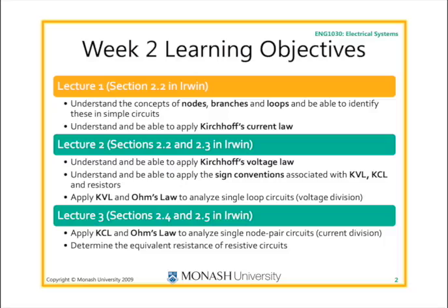Analyse node A, I'm going to say the sum of the currents entering this node is 0. Write down the equation in terms of the currents coming in. You could then jump to another node in a different part of the circuit and say the sum of the currents exiting this node is 0. That's fine. I think there it says you have to be consistent, choose a reference direction and stick with it for the whole circuit. Rubbish! You don't need to do that. Node by node, you can make your own decision. This node, the sum of the currents entering. This node here, the sum of the currents exiting. Just don't confuse yourself. Most people adopt one way of doing it and stick with it, but it really doesn't matter.